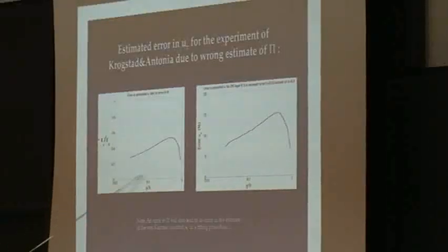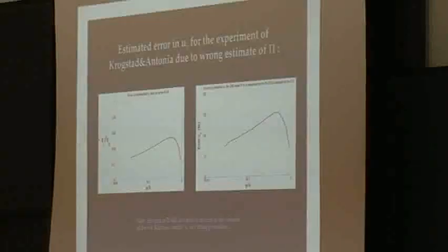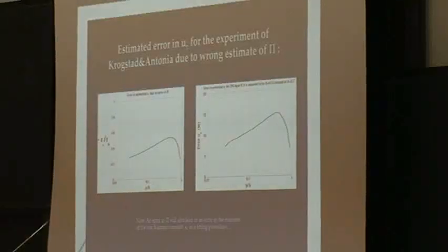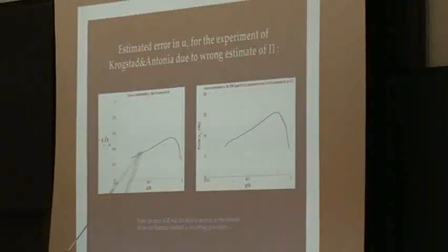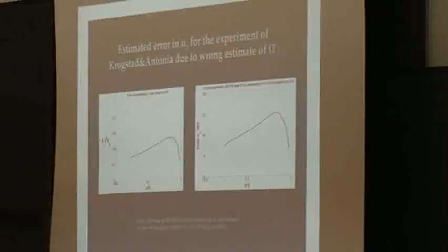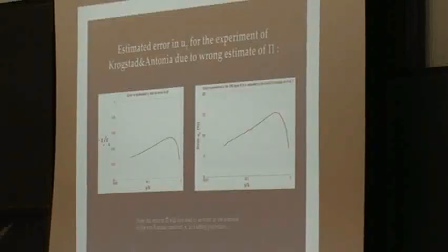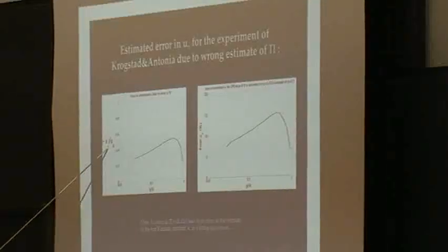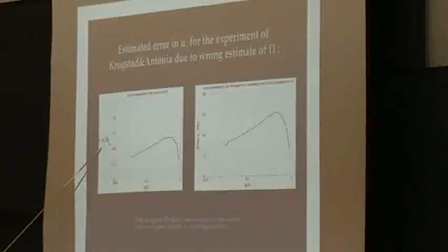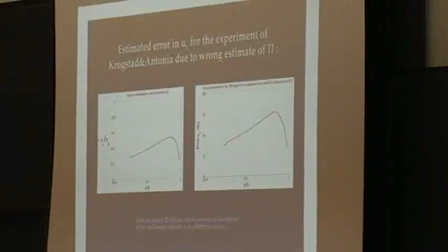This is a ratio, and it depends on which part of the profile you're looking at. Normally when we do this matching, if you just use the log law, you will be working in this region. If you do like I do and use the full profile, you will get something of the order of 40% uncertainty in the wall shear compared to the uncertainty you have in the wake strength.